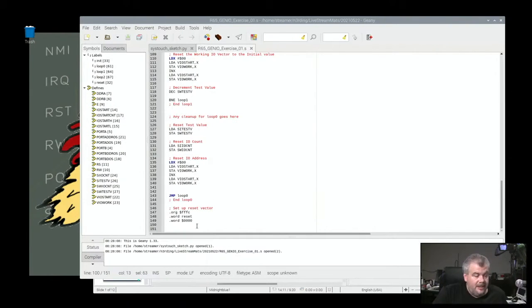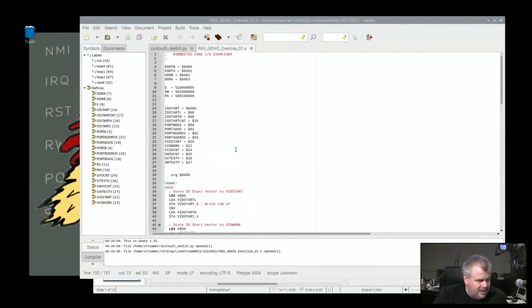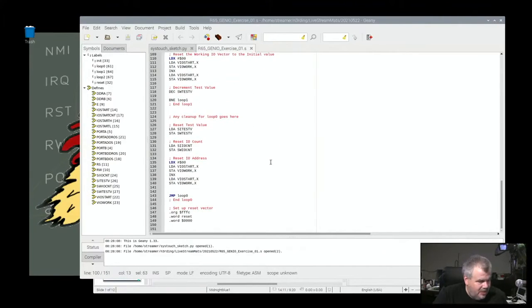And finally, this is setting the reset and interrupt vectors. So the interrupt vector is going to hex 0000, which is the beginning of zero page. Not the smartest, best thing to do, but whatever. Apart from the push button switch, there's nothing that's generating interrupts in this arrangement anyway. So at least currently. So that's fine. So this is the listing. It's with comments and white space. It's 150 lines. Not so bad.